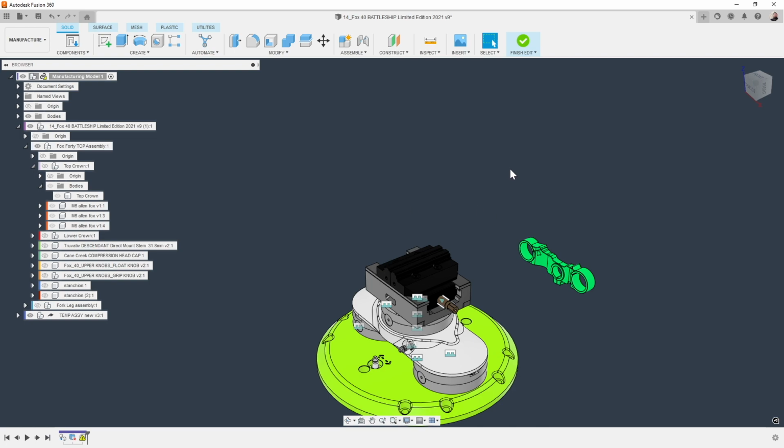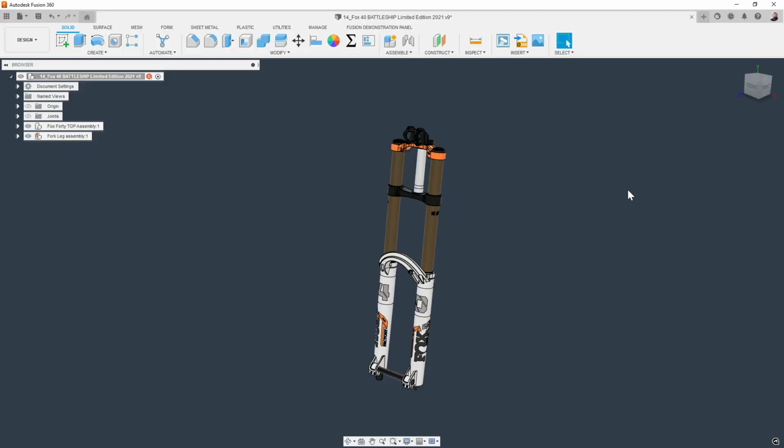Got it. So that point there, I guess, is manufacturing model isn't really using the CAD workspace to create sketches or extrusions, but rather you're using the manufacturing model workspace to add work holding bodies or components that the folks in the CAD workspace don't have a clue are in the file, which is great. Yeah, because you can see here, none of that stuff exists. That's awesome. And that's interesting.